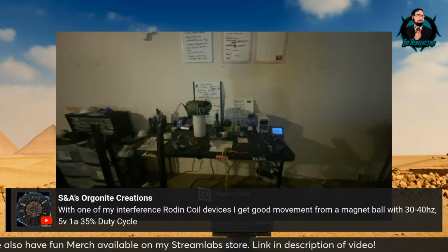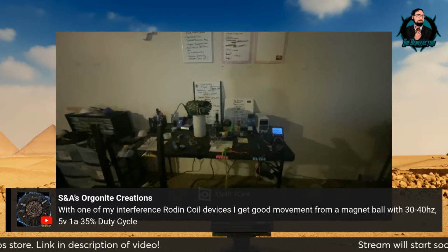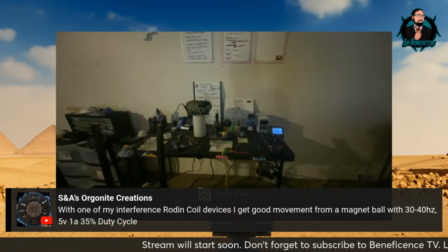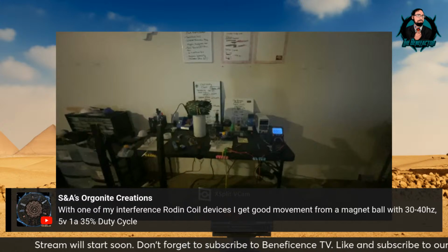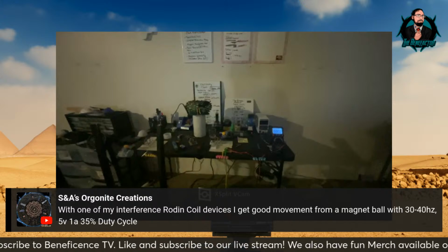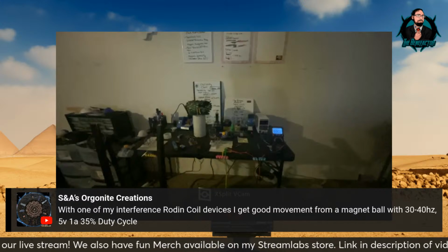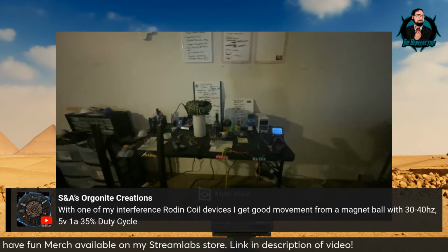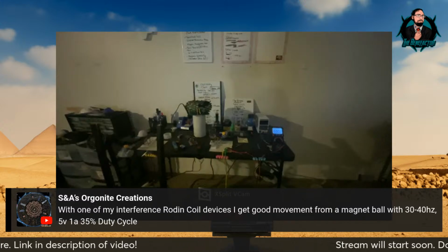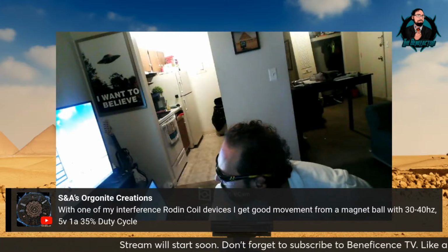I think the magnet is a neodymium magnet and a sphere, so I think it's probably not close enough to the edges of the sphere and its field, because the fields on these neos are very short range. If he had the same magnet, spherical but ferrite, it would spin no problem, because the field is much wider. So I think he needs a ferrite magnet, if not a neo-ferrite, just a standard square ferrite magnet to put in his hand and fish around that coil to determine where his field strength is when he's changing the settings. Because that's how I do it.